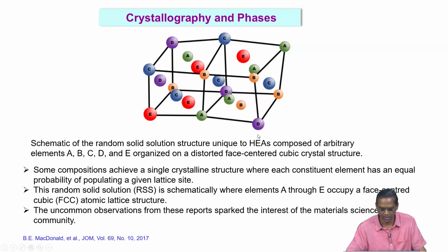Okay, very good. So, you have some lattice, but it is slightly distorted, but it is not randomized. But you do not have the same atoms here, you have different elements. Okay, this is important, right? So, this is called a random solid solution structure. Okay, when you do not have the same element occupying the lattice positions, it is called a random solid solution structure, but ordered. It is not amorphous. Okay, it is not disordered.